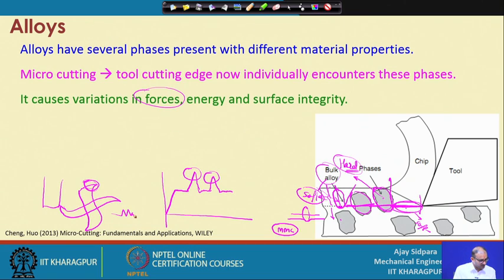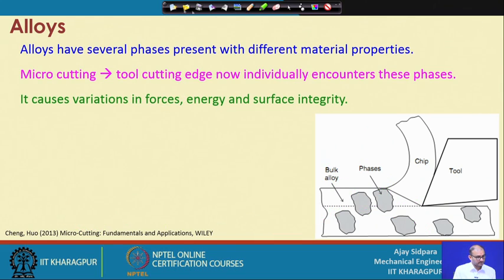So, you will not get that signal, and you get 3 peaks continuously, because in this 360 degrees you have one angle where the material is not present. That means this particular angle will not remove any material because the edge is not present there. So, in this case you also get the signal, but if we consider a single point cutting tool, where only a single edge is cutting the material, then you can confidently tell what is happening in this particular case.